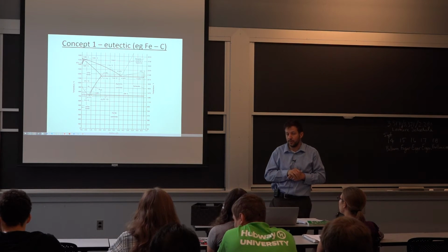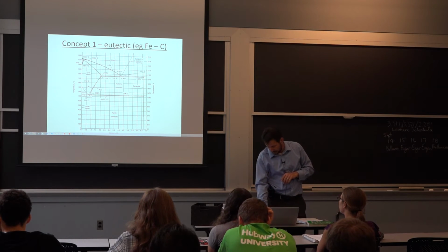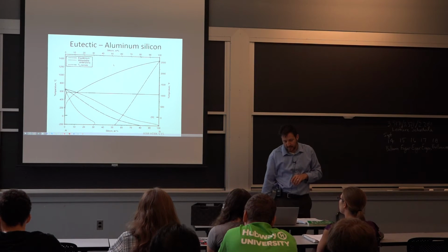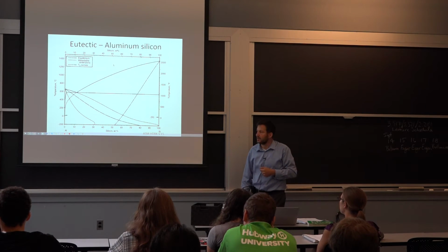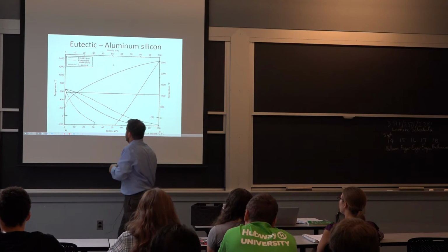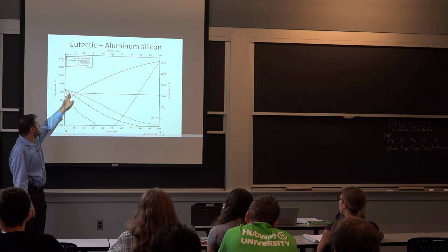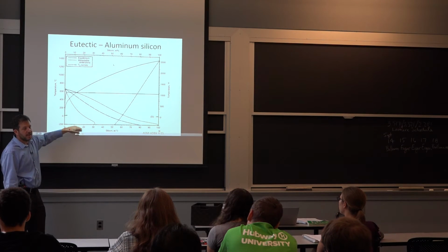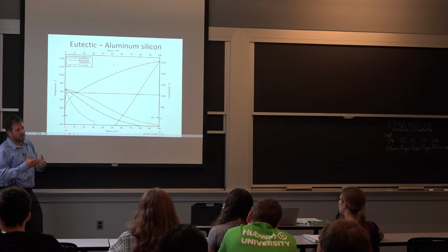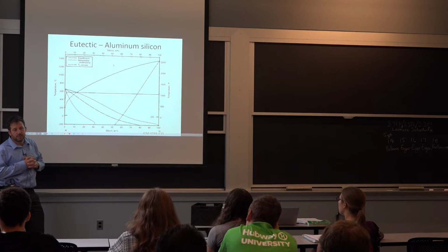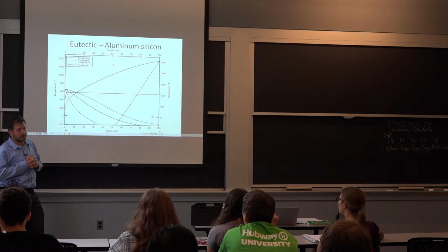You don't use a pure alloy. For aluminum, adding silicon is very common. The part that I circulated is aluminum with something of the order of 12% silicon. So your melting point is going down and you'll be forming a more refined microstructure from the casting than if you just try to use pure aluminum.